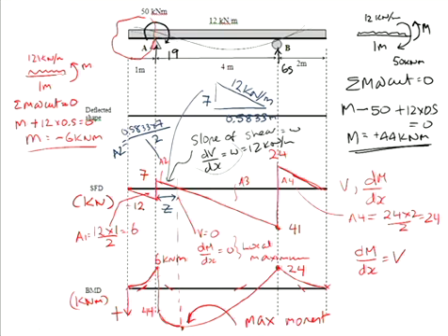So once again, if you are totally confused by what it is there, what you should do is actually cut the beam at 1.5833 metres. That's 19. That's 50. And when you take moments at the cut and you equate them to 0, that will give you a maximum moment here equal to 46 kilonewton metres. So that maximum moment is 46.